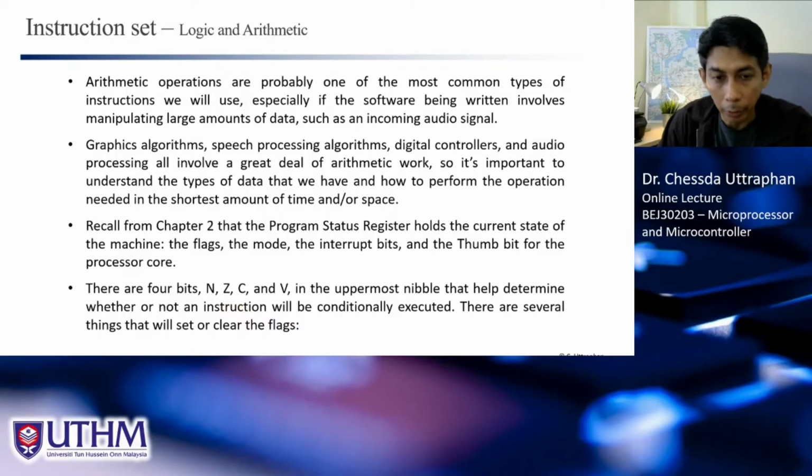because the microprocessor, as we know, is a digital hardware, and digital hardware has limitation, right? The size for storing the result is limited. For example, in our case, the size for storing the result is 32-bit. What if the result of an arithmetic operation is more than 32-bit? What is the action to do? When we say that our microprocessor is 32-bit, it means the result cannot be more than 32. It can be more than 32-bit, but we need to have extra work.